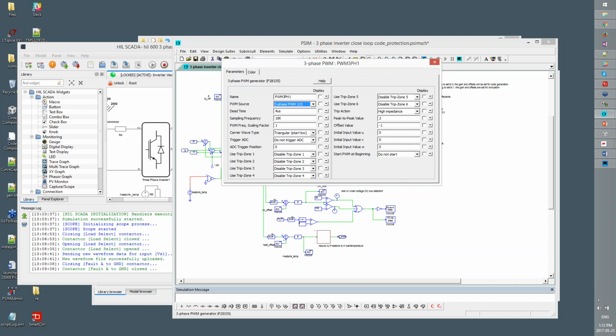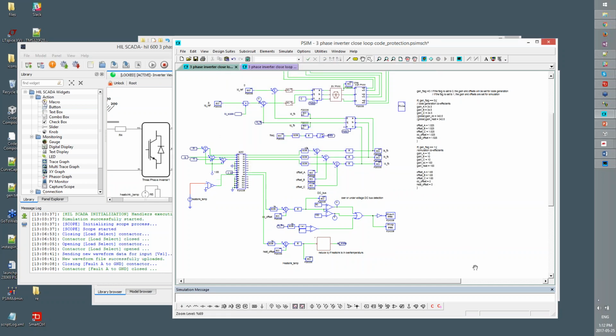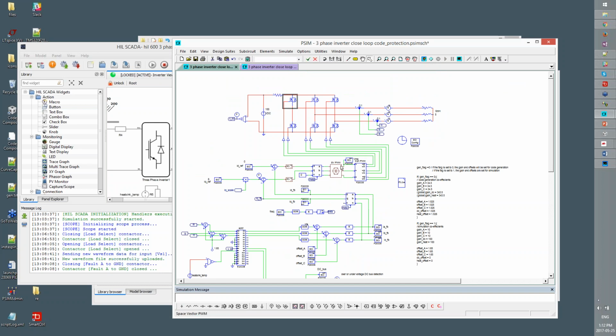The other things you're talking about, those nonlinearities, are not possible to be simulated in real time. Those add a huge amount of computational effort. Nonlinearities for switch delay and real devices turning on and off are not possible to do in real time. You can run those models in PSIM. We do have nonlinear and characteristic models in PSIM, but those simulations require a very small time step and take time to run.